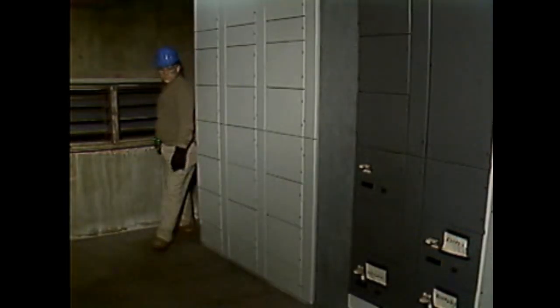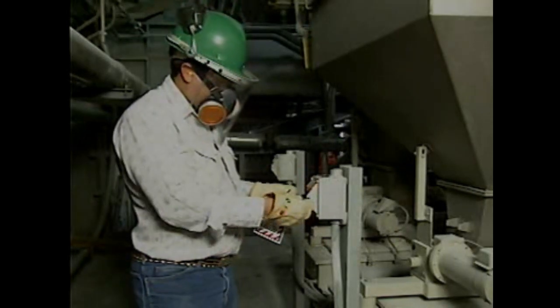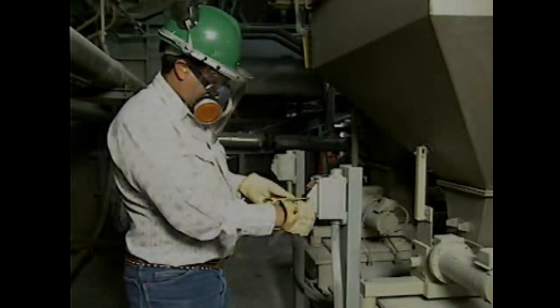When it functions as an isolating device, a circuit breaker is tripped by personnel to isolate equipment from a source of electric power. This allows equipment to be locked out of service so that it can be worked on safely. Another procedure, known as racking out a breaker, can be used to physically lock out a load from its source of power so that de-energized equipment can be worked on safely. Racking out a breaker involves physically disconnecting the breaker from its electrical connections.